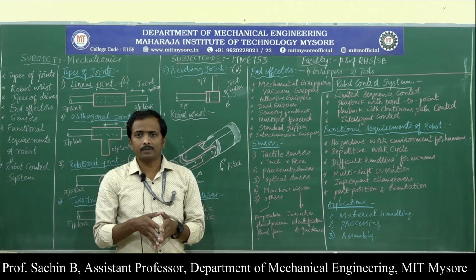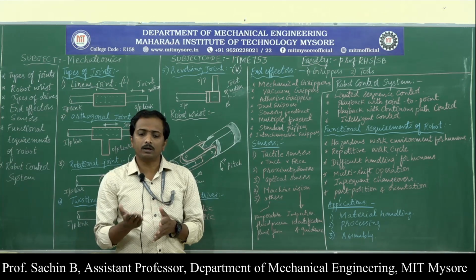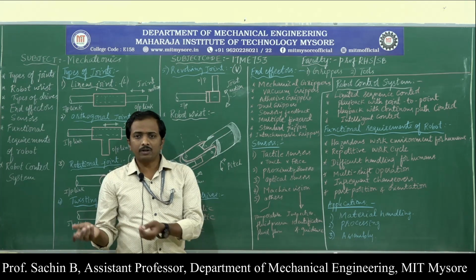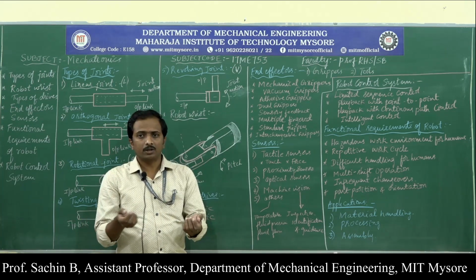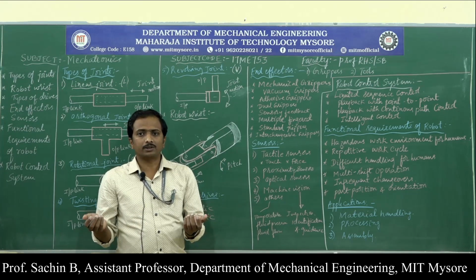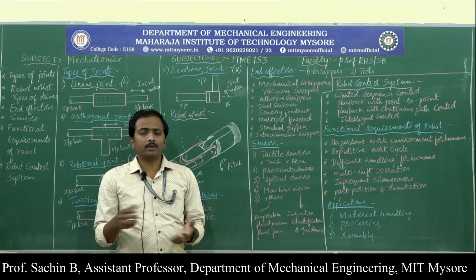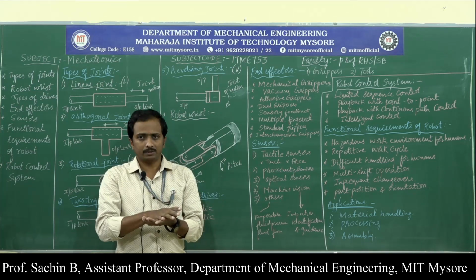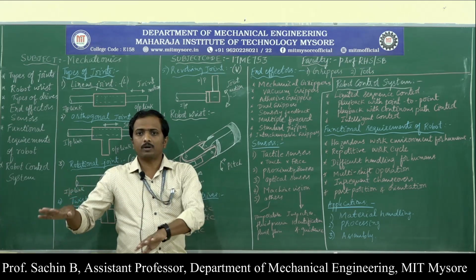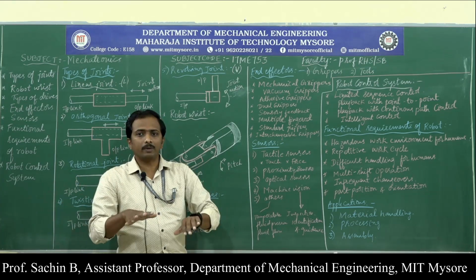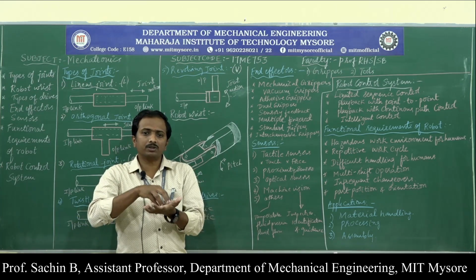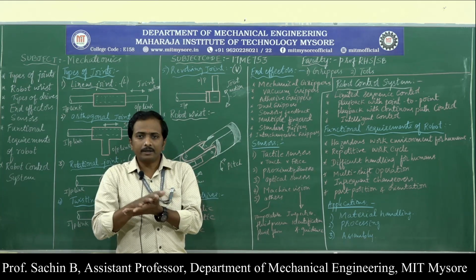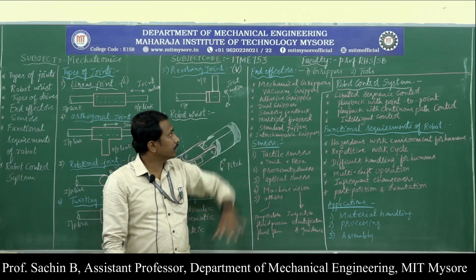Next, the vacuum type of grippers are used for manipulating or operating glass objects. It is easy for us to lift glass from one place to another with our hands, and there is no need for such grippers for us. But with robots, we need to create suction pressure to lift the glass plate from one place to another. The suction pressure is created, due to which those grippers get attached to the glass material and it can be easily moved. That's why we use vacuum grippers.